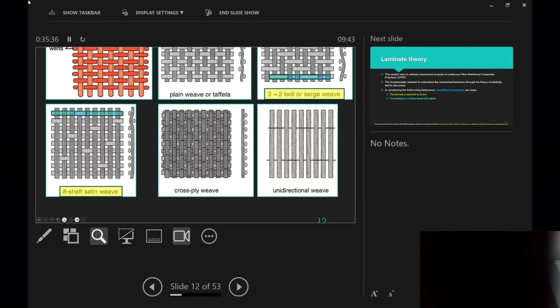That's the king that we use for high performance structures. Essentially, you've got fibers running along one direction. And because you've got fibers in one direction, the modulus of elasticity on these ones is around 70 gigapascal, and on these ones you get something between 120 to 180 gigapascal, depending on the kind of fiber. So the stiffness, not strength, is quite high because all your load-bearing components are running along the load direction.